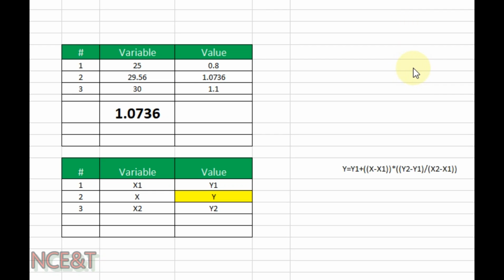As the pipe sizes in the hydraulic table are given only for standard values of GPM, we will again use the linear interpolation formula to select the pipe size, velocity and pressure drop for our calculated GPM values.